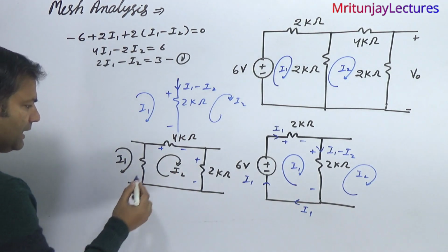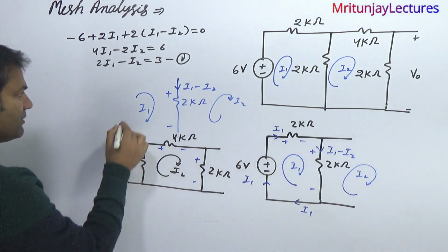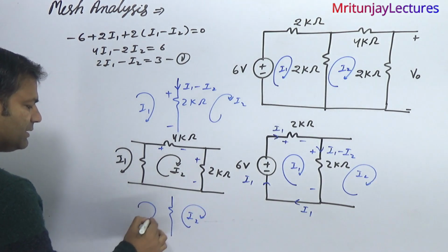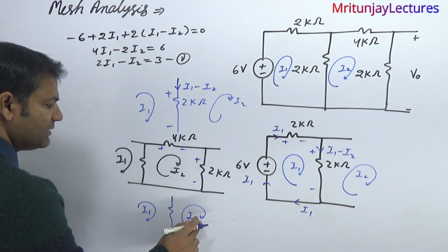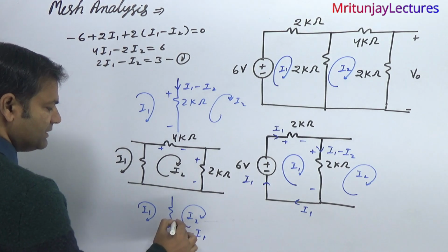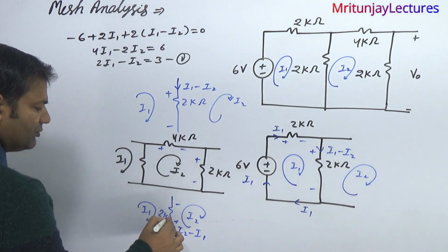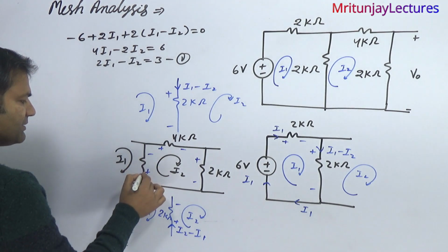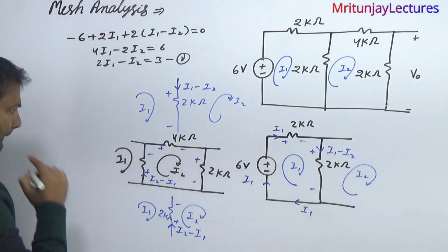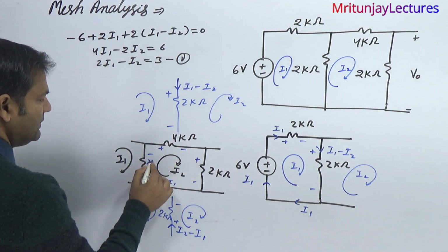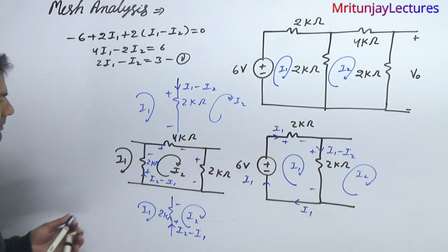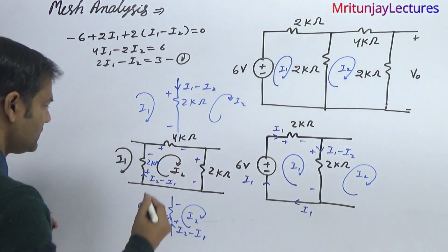But here if I2 dominates I1, means direction of same thing, here I2, here I1. If you consider this one dominates, here I1, means I2 minus I1, that is plus, here minus, and that is 2 kilo ohm. So that is plus, that is minus, and here the branch current is I1 minus I2, clear? And the resistance is 2 kilo ohm. Apply KVL in this loop. Plus to minus.